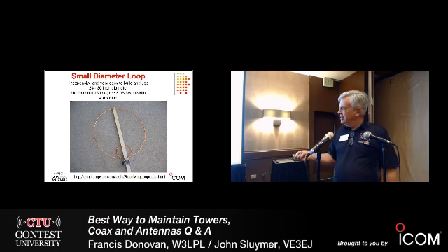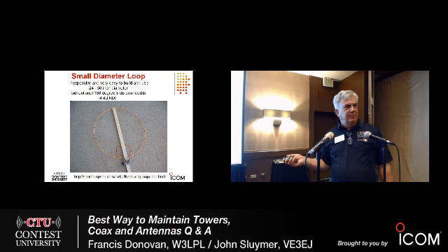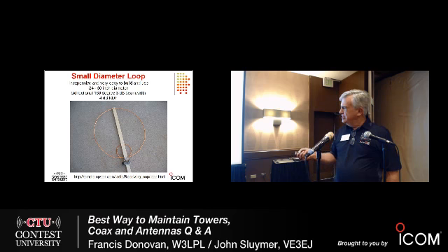If you attempted to receive signals on this loop without some mechanism to increase the impedance at the feed point, the signal levels would be extremely low. So this just raises the impedance. You could replace this with a little coil, just like we do on our Yagis. But for some reason, this has gotten a totally fictitious name of coupling loop, which it is not.